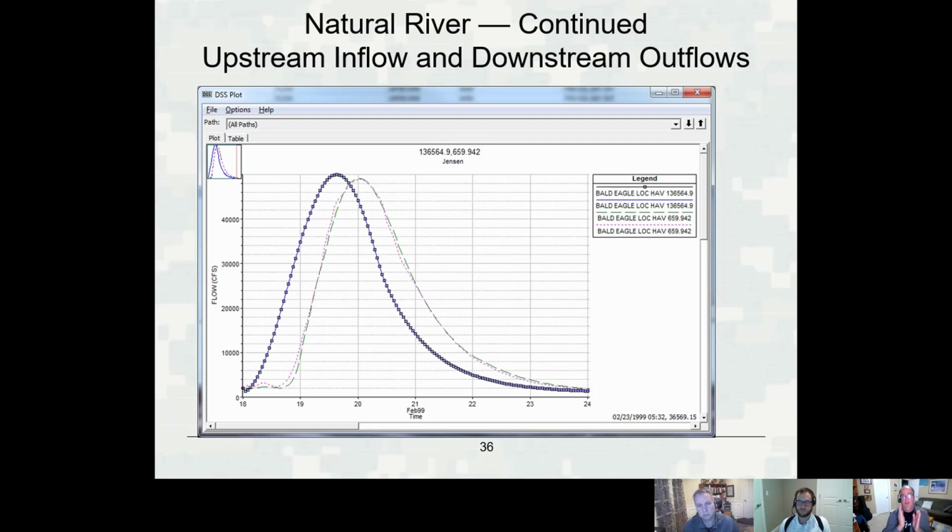However, one drawback of the finite volume method is that it's a volume method. If cross sections are super close together, then that cell has very little volume, and the water surface in that cell will rise and fall based on much smaller changes in flow. So if you have too small a spacing and basically too small cells, you're going to need to use very small time steps, because for a given time step, when it brings in a flow and a volume, it's going to want to go up more before it computes the outflow, and it's going to have to iterate more to get that right.